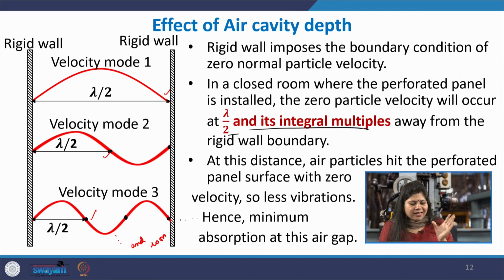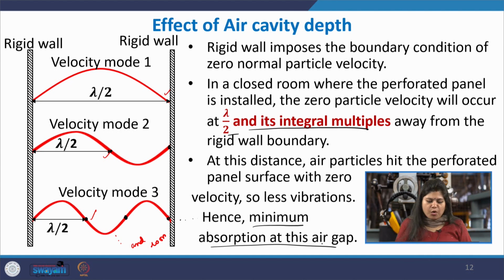So whenever that depth is maintained, the particles are hitting with the least velocity, and hence even if it is at the fundamental frequency, the energy dissipation will not be high because the energy of hitting itself is less. Okay. So in that case minimum absorption would be obtained.